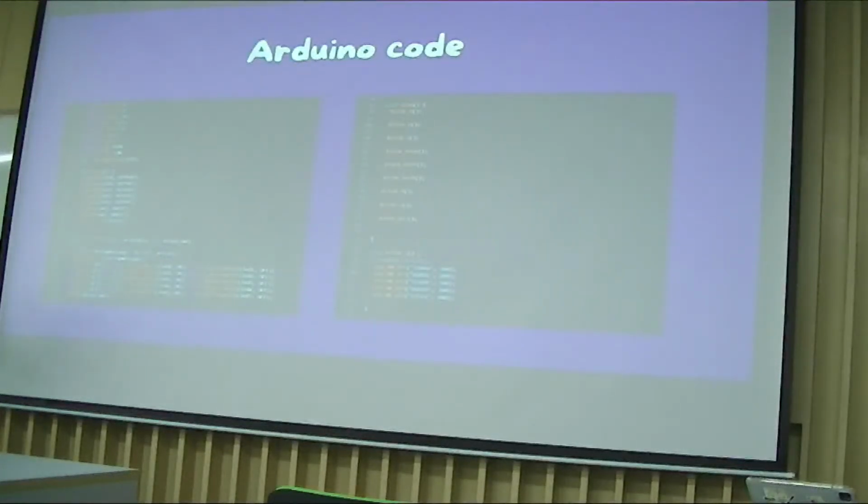And then for the void setup, this is where we define each LED as an output and define the switch as an input. For the LED on and off function, this is where we define each individual LED to turn on and off based on the input. The delay time parameter is used to put in a delay so it can make up our pattern.